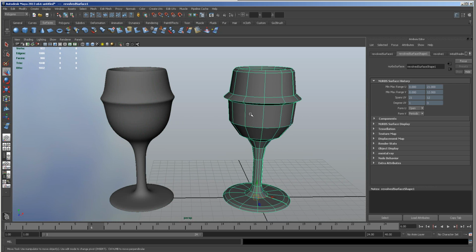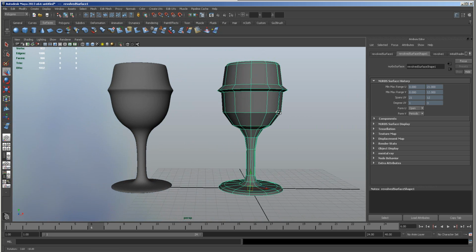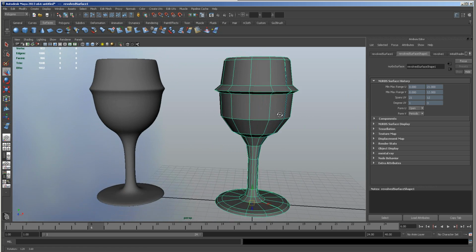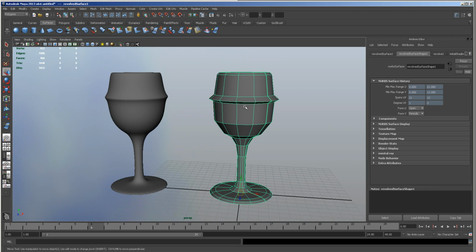It was talking about U and V coordinates and parameterizing and rebuilding curves, all that we've covered, but it just did it in such a complicated, convoluted way that it was quite hard to understand. So hopefully this course has made it a lot easier for you to understand the basics of Nurbs modelling, and from those building blocks, you'll be able to happily Nurb model away anything you like.